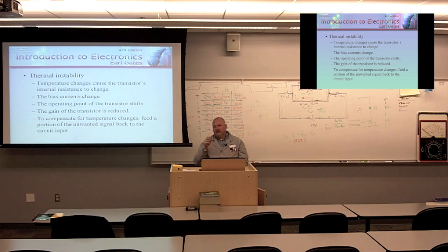When I speak into a microphone, it's creating electromagnetic energy, right? That's being transferred down the wire. That's going to be put into the input of the transistor. That small fluctuation is going to make that operating point change and amplify more, amplify less based on my speech pattern. And the key word there is amplify. So that's how speech pattern has an effect on the biasing of the transistor and thus the amplification of a signal. Make sense? So achieving that operating point is really critical.